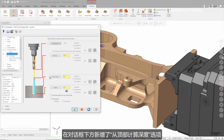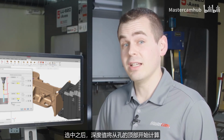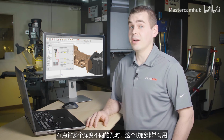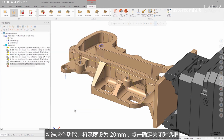At the bottom of the dialog, there's Calculate Depth from Top of Line or Hole. This checkbox lets us override where the depth value is calculated from. With this checked, the incremental value is now measured from the top of the hole instead of the bottom, which is very helpful for things like spot drilling multiple holes of varying depths at the same time. With these checkboxes set, I'll enter a depth of 20 millimeters and click OK to close the toolpath dialog.